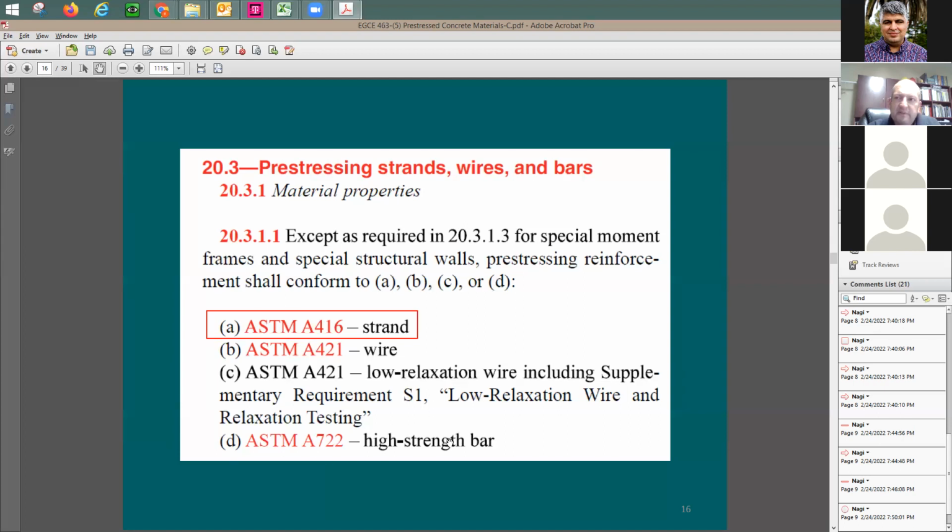The high strength bars, you're going to see them, let's say, in the structures lab, and in certain applications like railroad construction. If it comes to pre-stress, you're going to see it in metro projects. You're going to see this high strength rebar, and it is going to be big in size. We're talking here about more than an inch. The standard that you're going to see there may be an inch, an inch and a quarter, an inch and 3/8. So these are real big rebars with high strength. This one you really need big force.